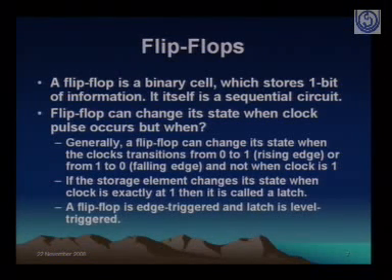So these are some of the things which we discuss as far as flip-flops are concerned. A flip-flop itself is a sequential circuit, but one of the most important circuits as far as creation of devices in computers is concerned. And one of the most common devices in a computer system which you create is the counter, because that keeps track of various states. Now we first start with the latch, which changes its state when the level is there, or one level is there. So let's try to define the latch, and then we try to define the flip-flop. A latch is typically a combinational circuit.